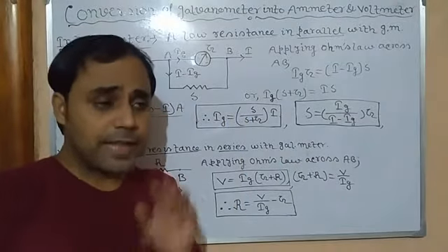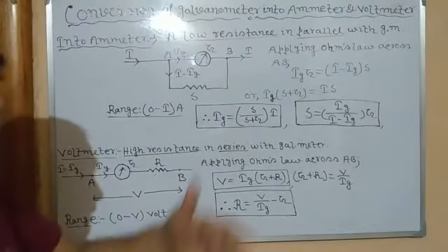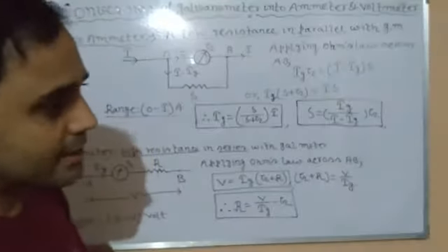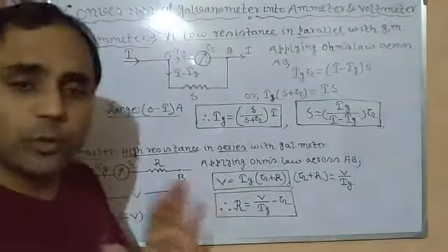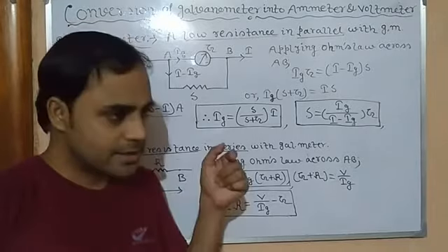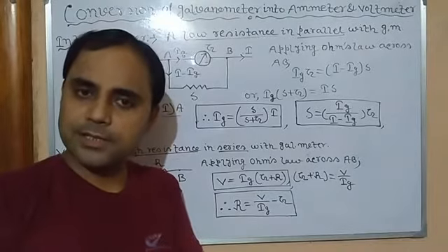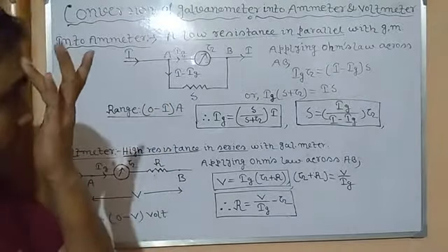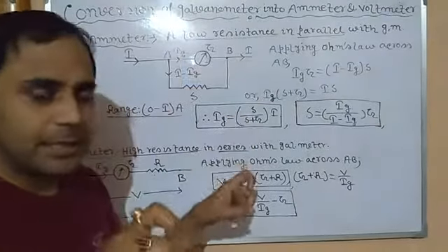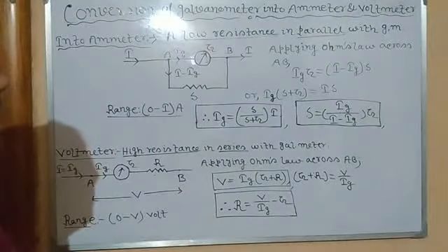Since its function is to measure the actual current through the circuit, the ammeter should be connected in such a way that the entire current flowing through the circuit can pass through it, and it is only possible in case of series combination, because series combination provides only a single path of flow of current. And why is the voltmeter connected in parallel? Because the voltmeter generally measures the potential difference across two points. So that's why the voltmeter is generally connected in parallel combination.